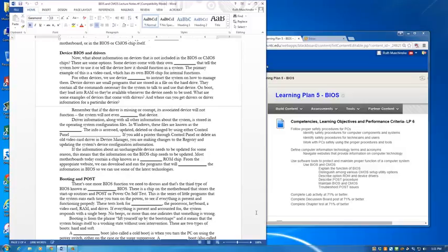So these tests look for power, the processor, a keyboard, video of some kind, RAM, and drives. If everything is present and accounted for, many systems will respond with a single beep. If there are no beeps or more than one, this generally indicates that something is wrong.